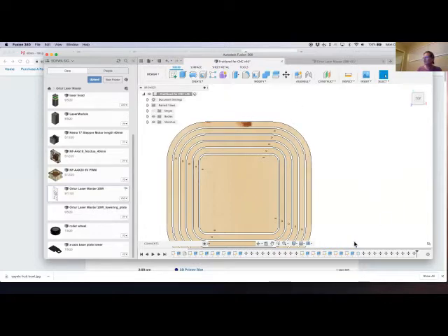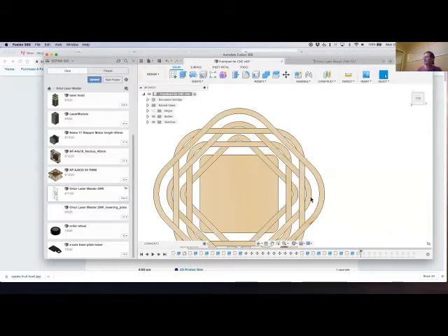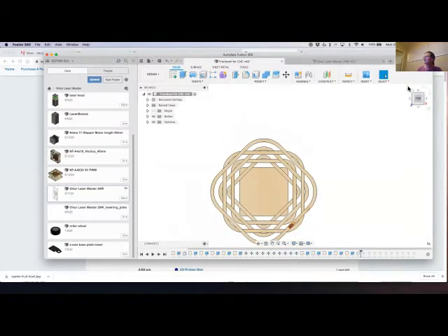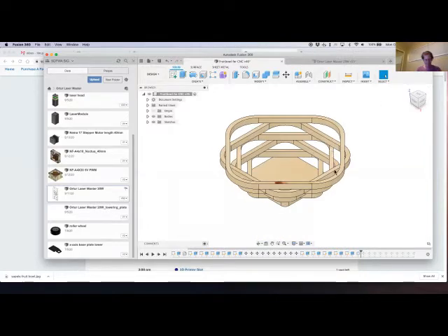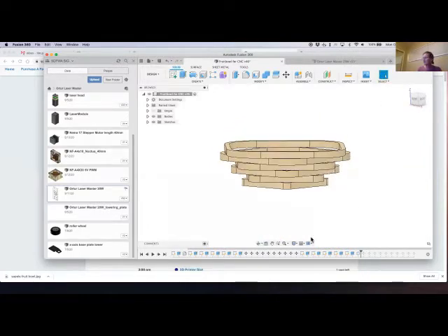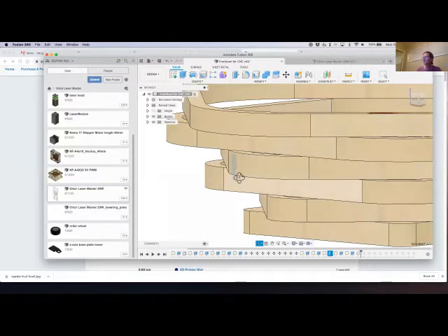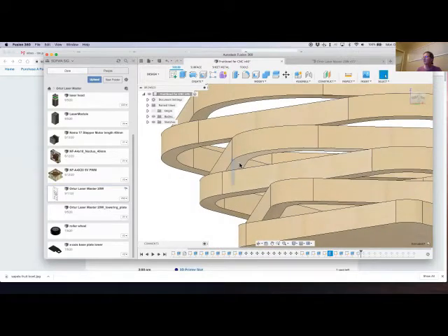And what happens is, let me pull this back to here. So what basically happens is I define the sketch plane. Let's say we look at this pin right over here. The sketch plane for this pin is this surface here. So I pick this surface and then I place the circle and I dimension it from the outside edge of the smaller tier and the inside edge of the larger tier.